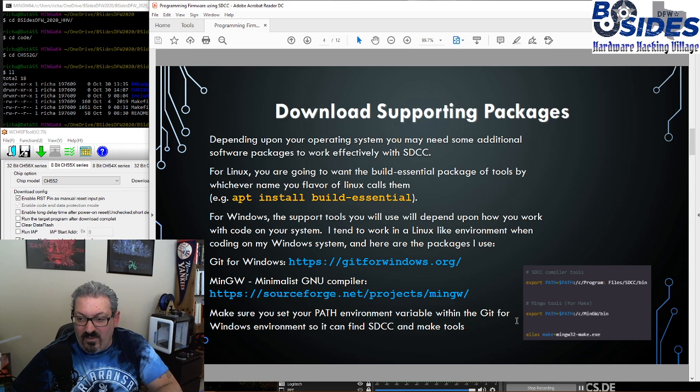And then in whatever environment you're working in, you're going to want to make sure you check your path in Windows. Windows paths are very particular. That way we tell it where our SDCC binary files are, where MinGW is, and where our makefile is that we're going to use. So depending upon your Windows system, you're probably going to have a different setup than this. And I'm assuming that anyone watching this video is not new to compiling or programming altogether. You're just wanting to learn about the SDCC specifics, and that's what this presentation is pointing towards. So I'm not going to go into any more detail there.